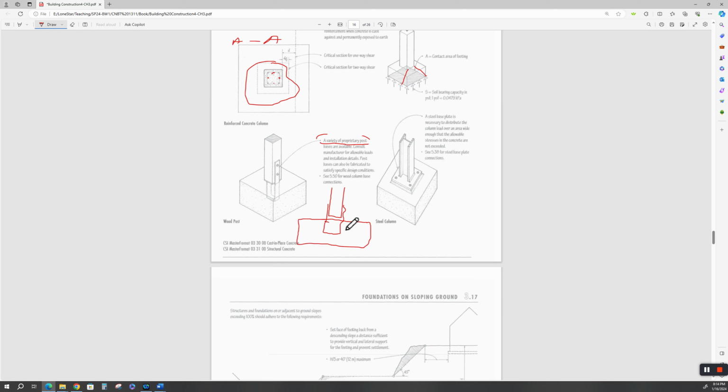You are going to want a space underneath that wood column and the surface of that concrete, so that when it rains, that water doesn't stand underneath there and rot the bottom of that wood column out. And that column is only supported by those bolts in shear. So it's not going to carry a whole lot of load.